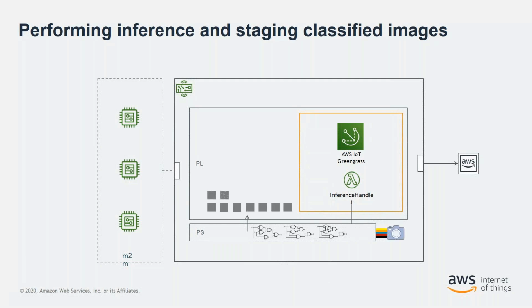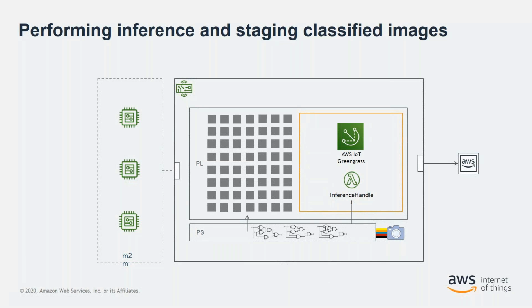And once you start doing the inference work, then you'll start getting results. Now, say, for example, we're trying to take a look at an inference where we find a human being in that compressor house that we talked about earlier in the talk. And if we see a person, we want to start loading images onto the local machine, right? Because eventually what we want to do is alert someone that there's someone in that compressor house, right? So we're actually taking the video feed that's going into the FPGA, it's doing the inference work, and then shooting back out through shared memory the images that it's capturing with the person that the machine learning model detected.